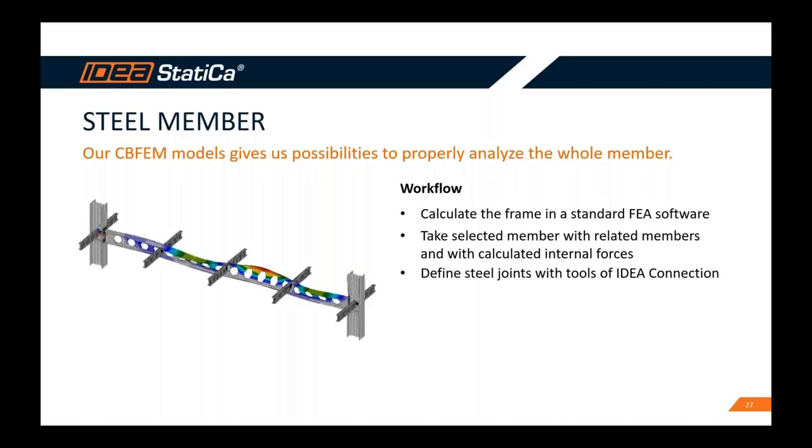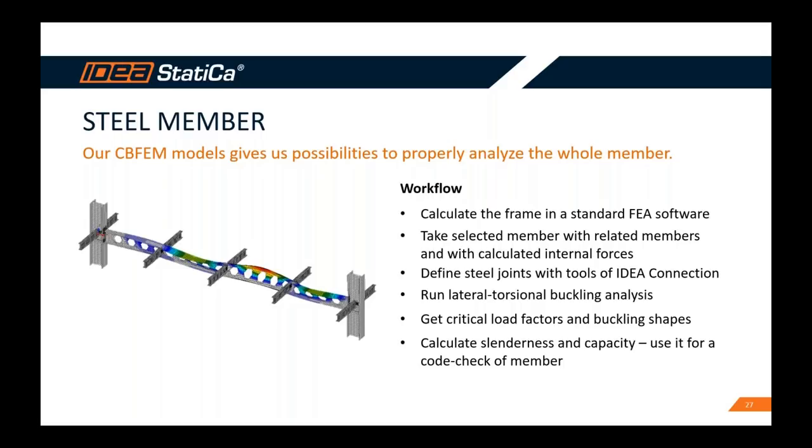Of course, do the connections in IDEA Connection, but then run the lateral torsional buckling analysis for the whole component, get the critical load factors, buckling shapes, slenderness, capacity, all that you need for a code check for that whole member.